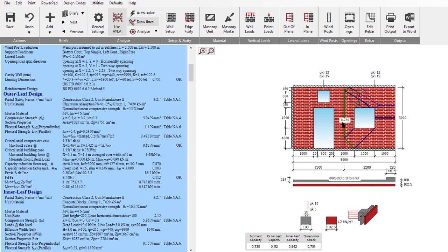When the yield line is going straight through the wind post, perpendicular to it, then that post has gone plastic, and that's a yield line with that post having yield at that point. But that doesn't mean it's failed. That just means that it's all part of the overall ultimate limit state yield line. That is the weakest, and then you obviously back calculate what your load factor reserve is.